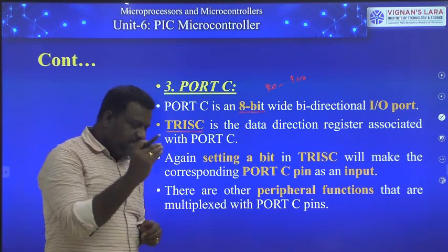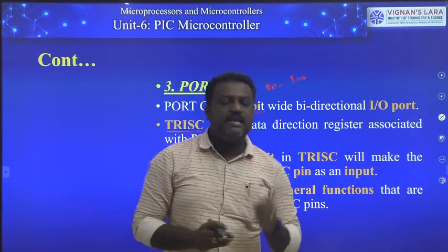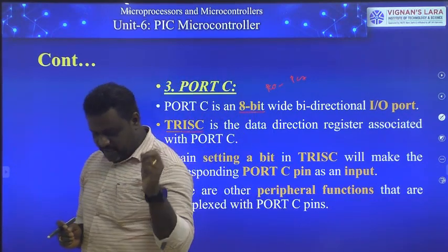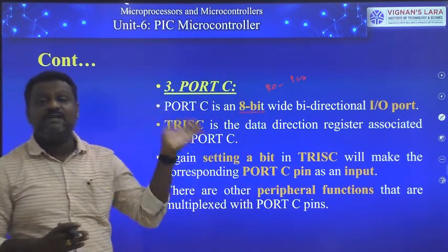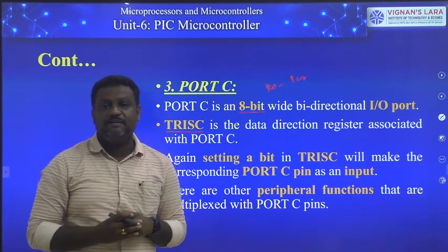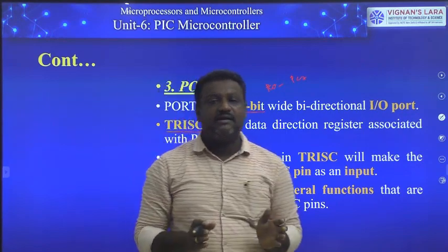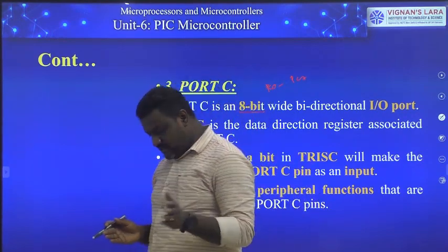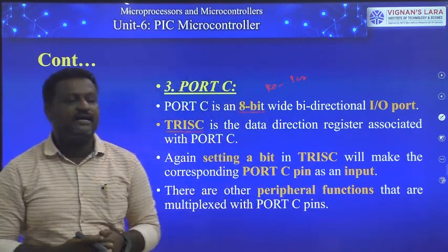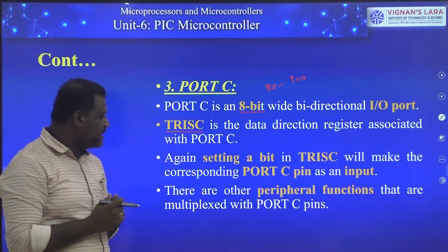That means any bit of TRISC that is set to 1, the corresponding pin in port C is defined as an input, and any bit of TRISC that is cleared, the corresponding pin in port C is defined as an output. So that is the same thing.